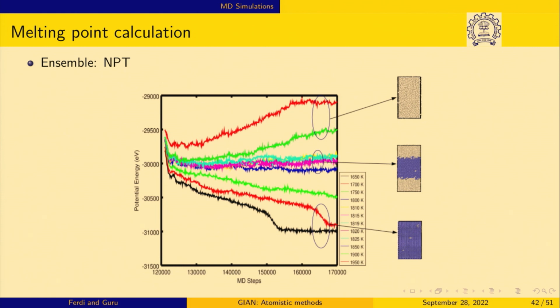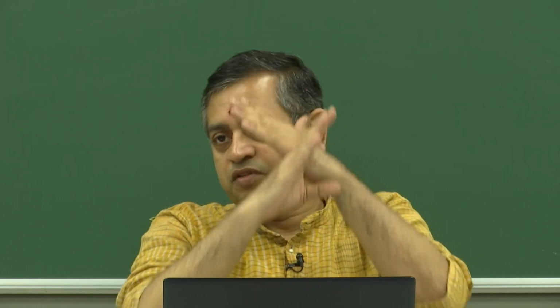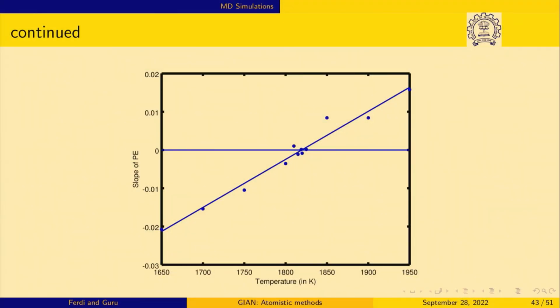I mean, kinetic energy also you can take, because total energy is a constant. So, you will see that it is remaining constant, but this potential energy is how typically it is done, and you see that wherever the solid liquid interface is at equilibrium, then you know that neither the solid is growing nor the melt is growing, which means we are at the thermodynamic equilibrium, the free energies are intersecting at that point.